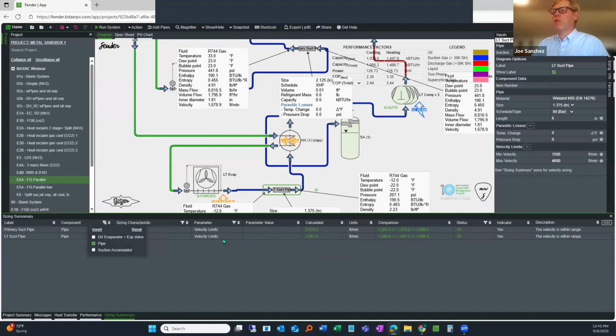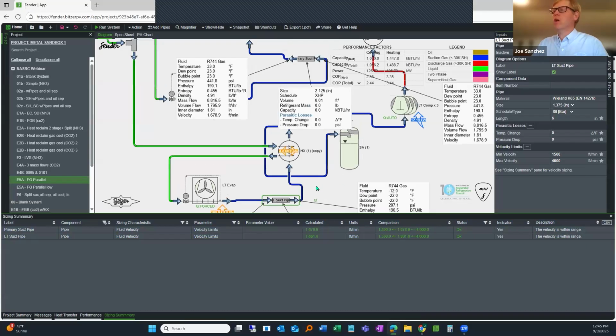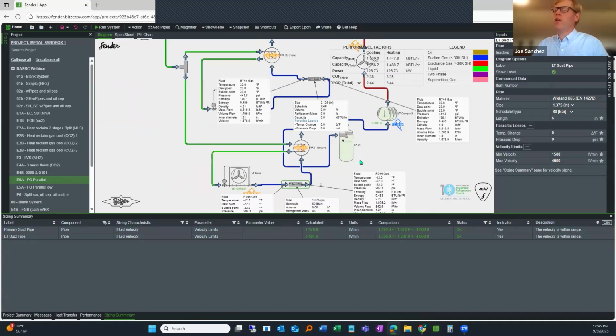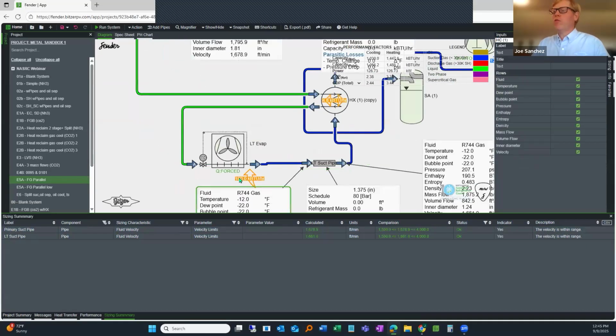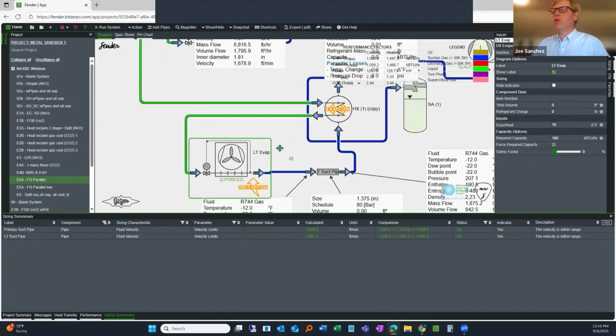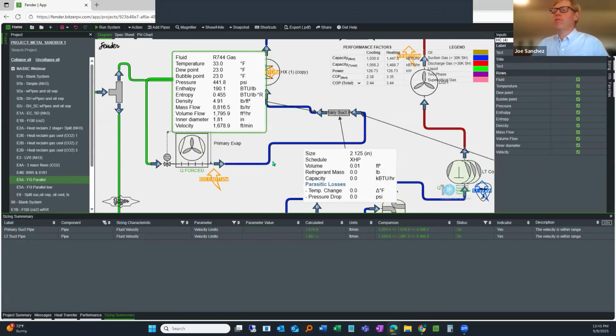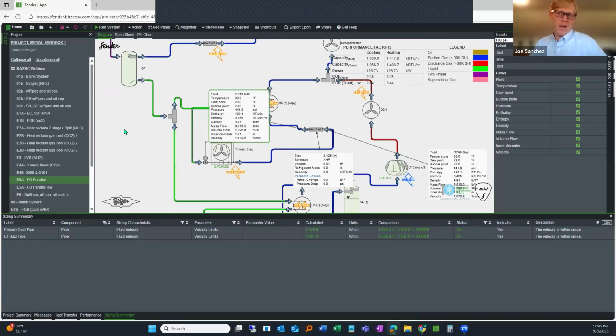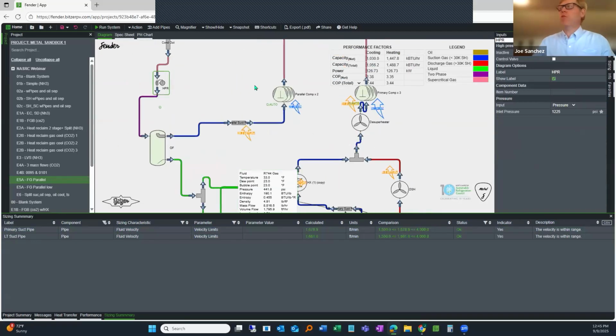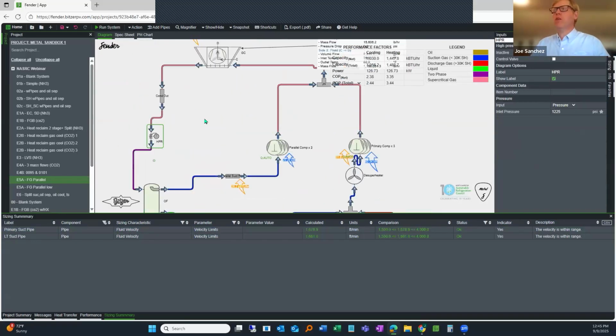Just kind of look at these two pipes that I'm in my range, a little bit on the low end. And let's see what happens. So if we go to a low load condition, right? Right now we have 180,000 BTUs in this evaporator and 850 in this one. Low load, maybe they cut by a third. Maybe this goes to 80 degrees condensing.